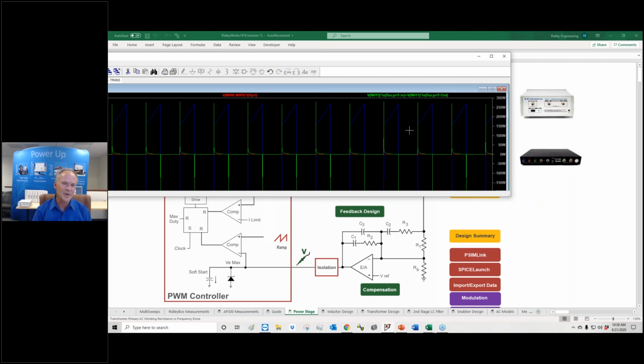So this is a case where going 3 layers is too far. 2 layers is about the right number of layers in here to minimize this loss. But we're doing everything now, not looking at the curves. We just go into LTspice, and we make a transition from the winding to LTspice really quickly. So if we want to change that winding, so what do we get here? That was 1.9 watts.